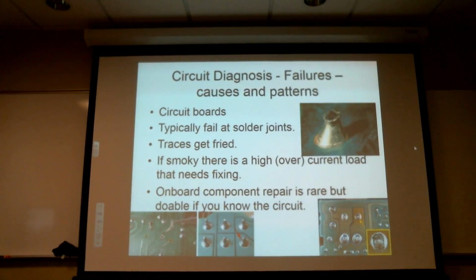I will tell you that a cold solder joint like that is a design problem. That's a manufacturing design problem. So if you see cold solder joints like that, particularly in an airplane, it might not be a bad idea to go on the FAA website, pull out an SDR, service difficulty report, and fill it out. Say, cold broken solder joints.